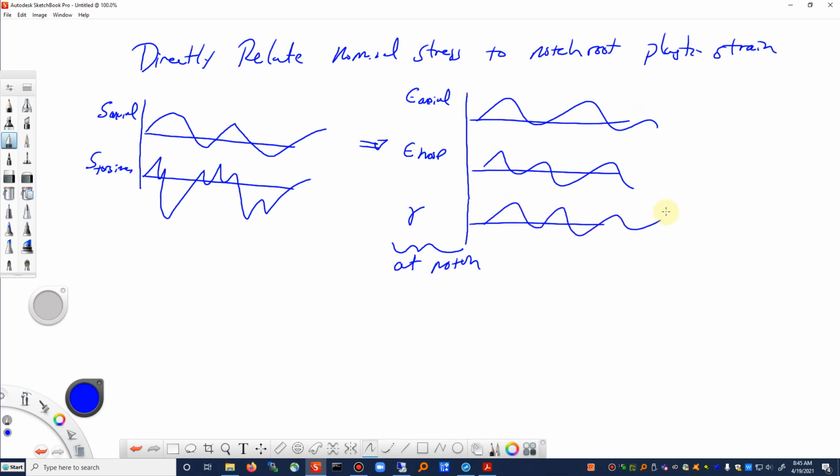Now, what are the downsides to this approach? Well, if you have a whole lot of plasticity, then there's no enforcement of equilibrium. Equilibrium is assumed to be where you have a little bit of plastic behavior surrounded by mainly elastic material. So you don't want to have nominal stresses that are just too high. Of course, from a fatigue point of view, if you have really high stresses, you're yielding a lot of material, your fatigue life is going to be very short anyway. So from a practical application point of view, this idea of the structural yield surface is pretty neat.